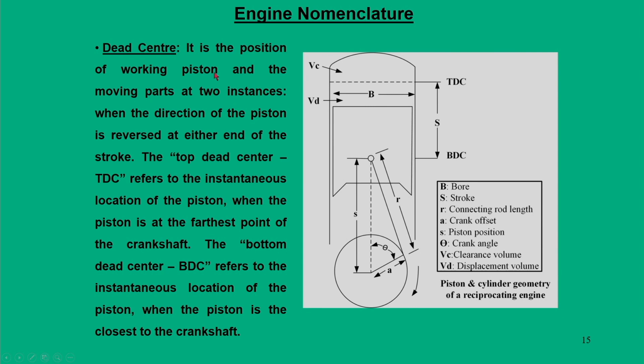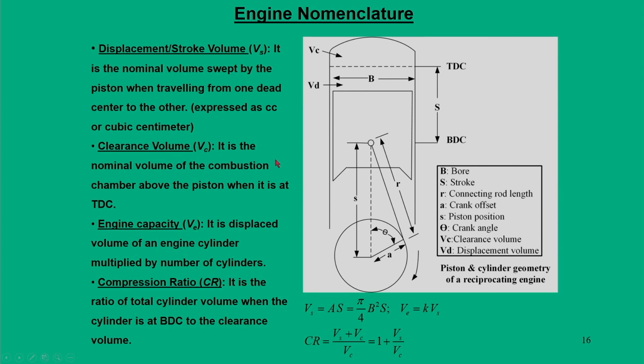Also I mentioned the word dead centers. It is the position of the working piston and the moving parts at two instances, when there is a reversal in the piston direction. One we call top dead center, TDC, and the other bottom dead center, BDC. These are the terminologies which we will be using frequently. The next